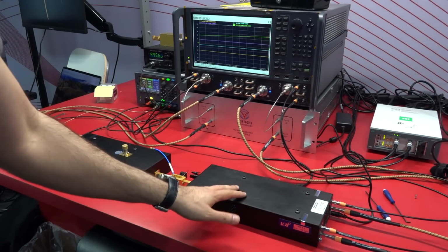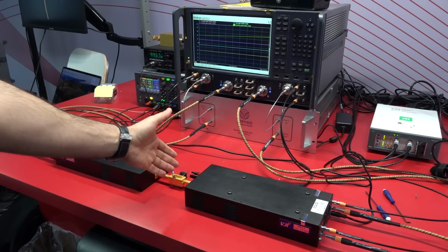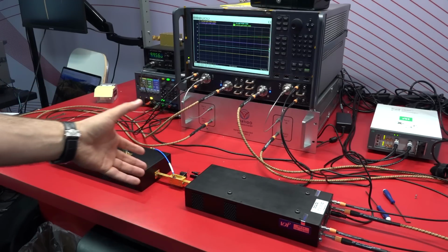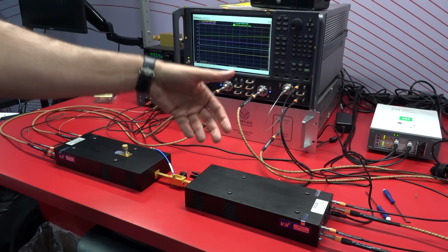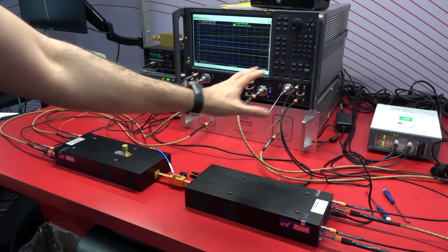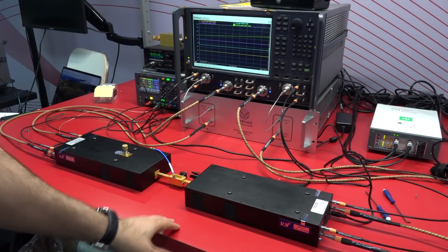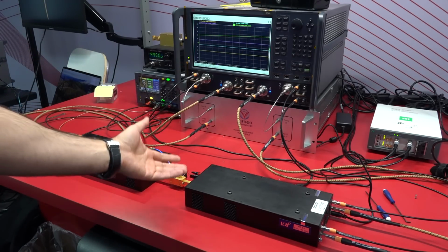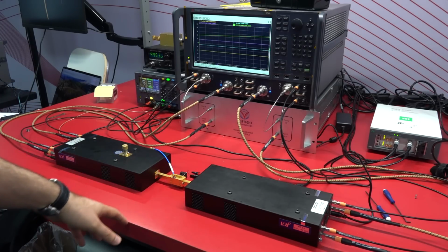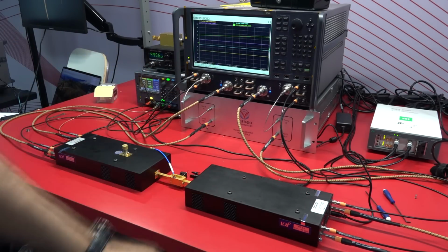So you're basically controlling the IF signal, but because you control them after calibration, you can create an incident wave that you want directly at the output or input of your device that you're testing. So you can create a load pull situation now using these extenders without having to worry about anything else in the background. You calibrate, and then you pick up whichever one you want. You have all the script written, all the calibrations available. You can do load pull on the Smith chart, 110 to 170 or even higher bands. It's become so much easier to do these load pull measurements, especially active ones. Active load pull measurements certainly have come a long way, but making a simple system to leverage what you already own, I think that's a pretty good idea.